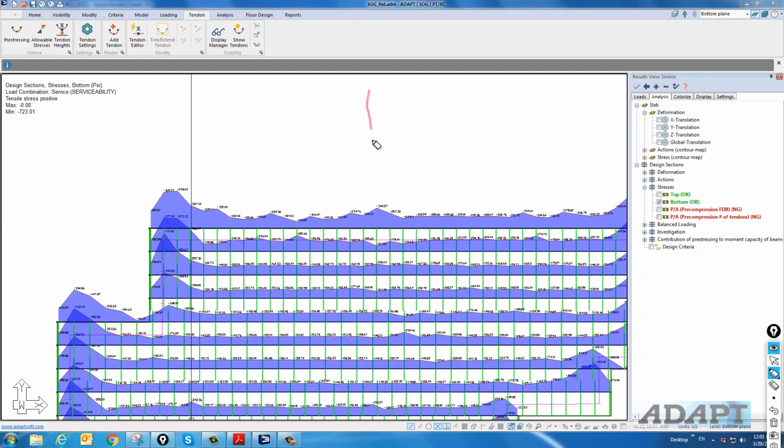If I look at a design cut and I have, let's say, a situation, typically when we bend this piece of concrete, again, we get tension in the top, compression. If I take a cut through there, we might get a stress distribution that looks like this. This is compression, this is tension. This is purely based on the flexural component.